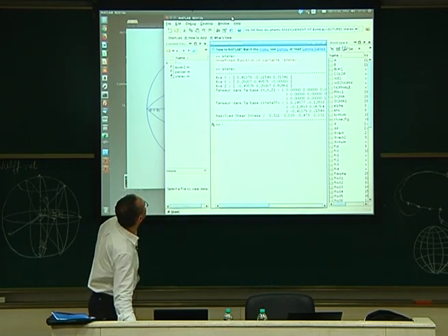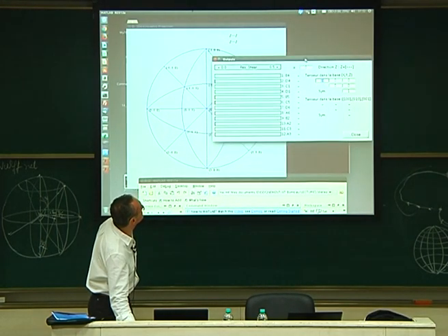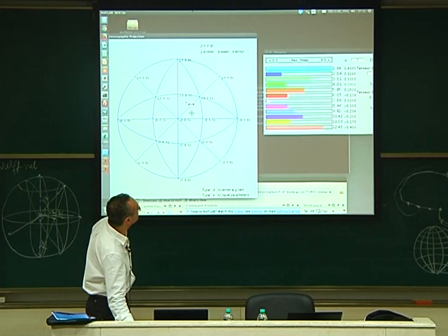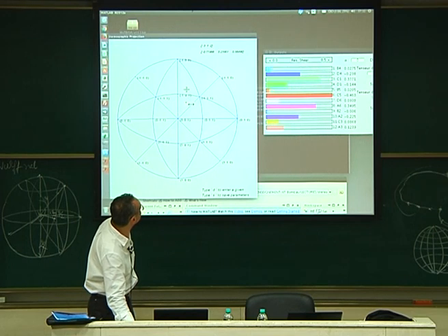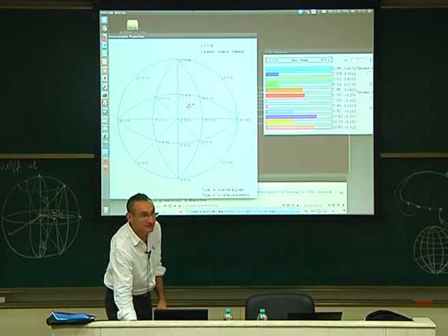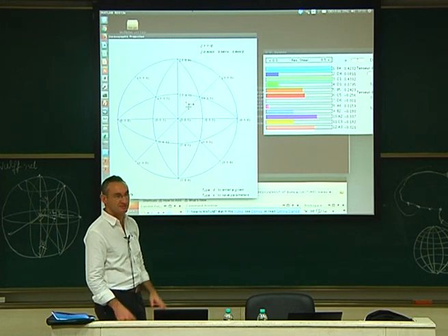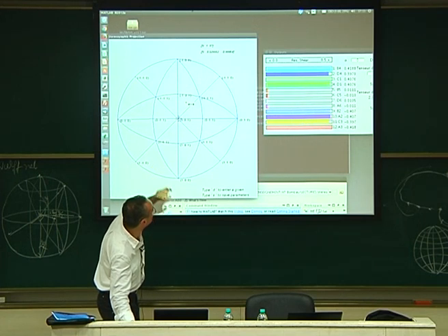So this is something I think we use much in order to exploit the high symmetry of BCC and FCC crystals. We can figure out that way all the possible orientations, depending on where you are in your material, when you are loading your samples, what will be activated. So you can see 2 things. When we are in the double glide configuration, typically when we are here, at that place, although you have 2 which are mostly loaded, the others are also a little bit loaded. So it's not a highly symmetrical axis. This is the information I want to give you. When you are here, you have 8 active and 4 not active at all.